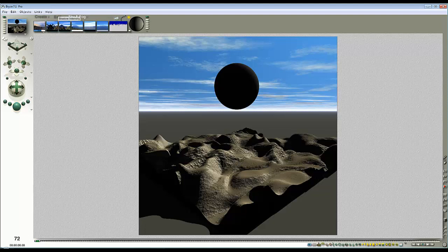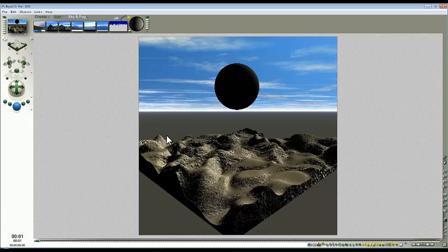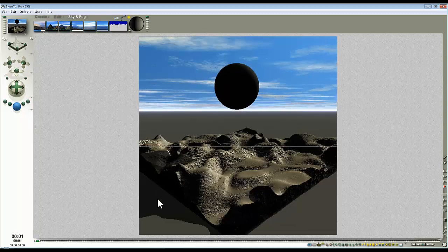Left click and we can reduce it down to its lowest value, and that takes the shadows cast from the geometry away. You will still get shadow regions appearing as a result of the light not arriving on that side of the geometry. That's a different matter, but this geometry should be casting some shadow on here, and how much shadow it casts, say set it to 50, will be letting half the light through. So you can see that area's light, that's in full darkness.